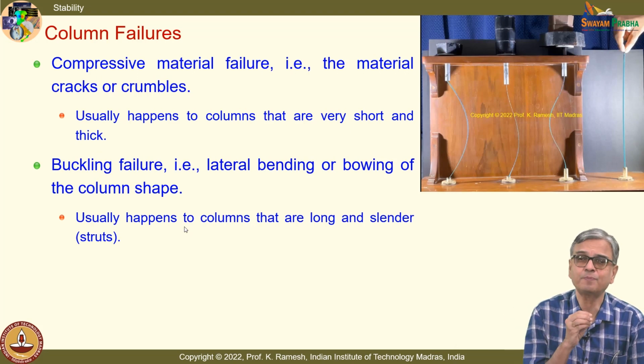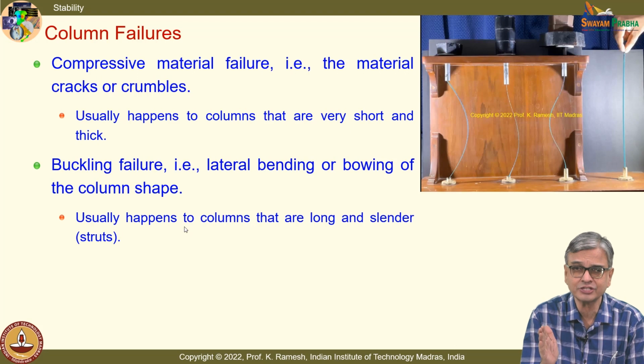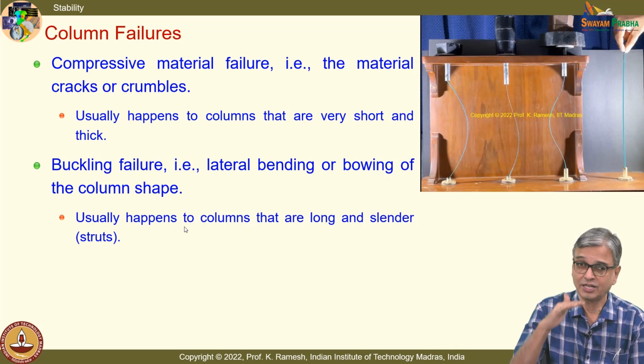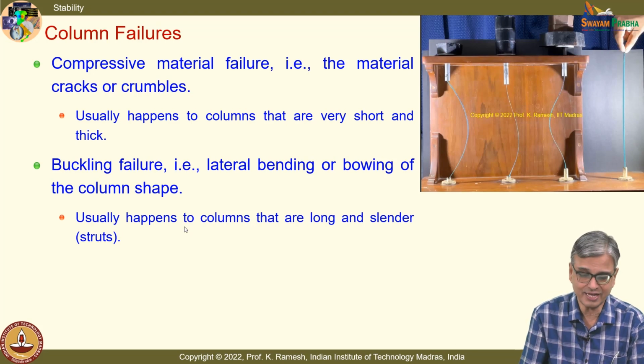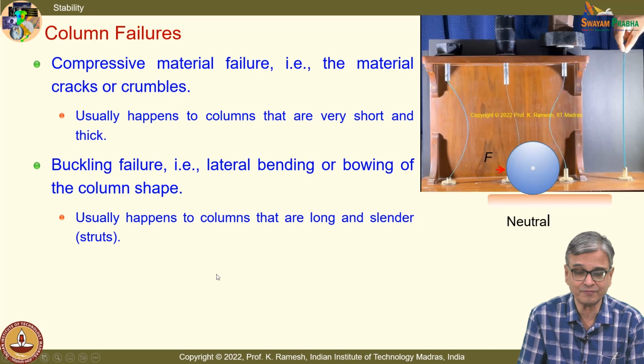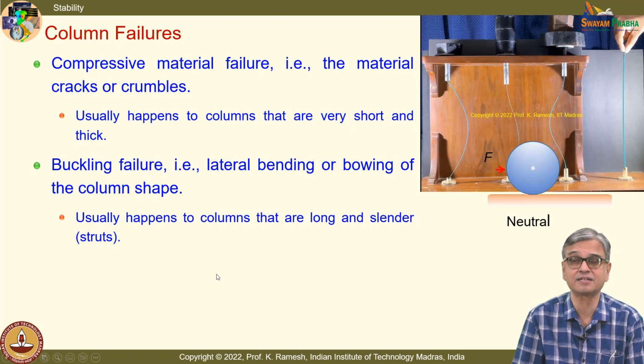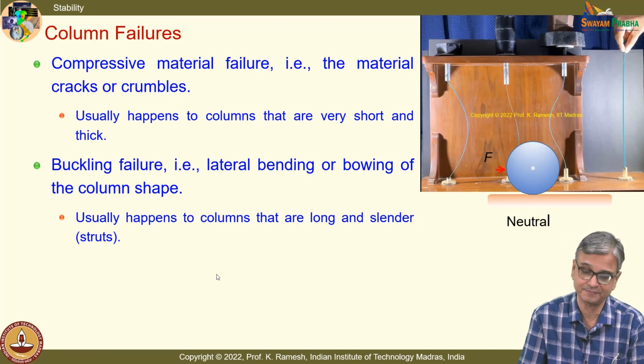Okay. So, what people have done is, they have done the mathematical analysis and also based on experience, they find there is a load which is labeled as a critical load, beyond which, if there is any lateral disturbance, even a small disturbance, it will go into buckled shape. The load by itself does not introduce buckling if there is a disturbance. Okay. Now, the question is, from where does the disturbance come? That also had to be looked at.